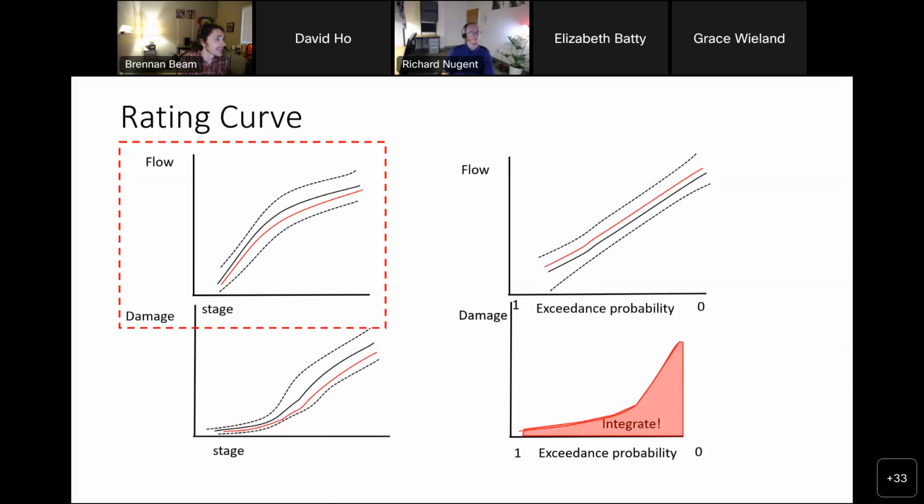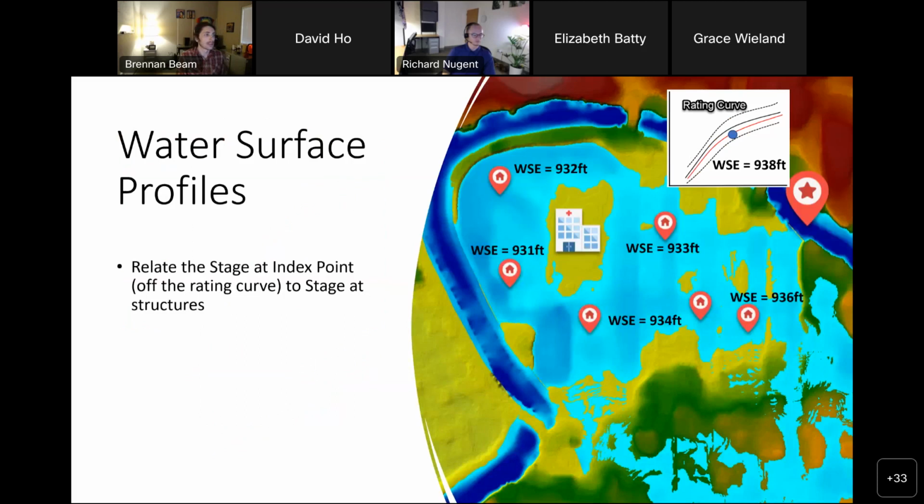That rating curve is the flow-stage relationship, which is the top left quadrant of our 4-chart FDA classic representation. Now, the other big hydraulic input, so we talked about the rating curve, is the water surface profile. This can come in the form of depth grids or water surface elevation grids, more accurately. It can also be extracted straight from RAS results in FDA 2.0, but it is a list of inundation profiles for different events, is really all it ends up being.